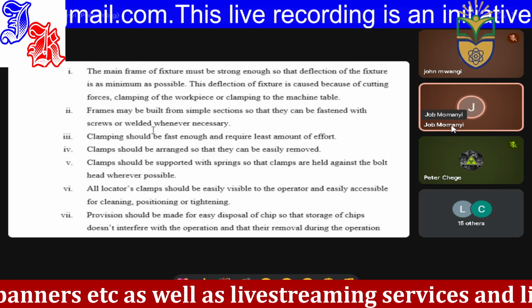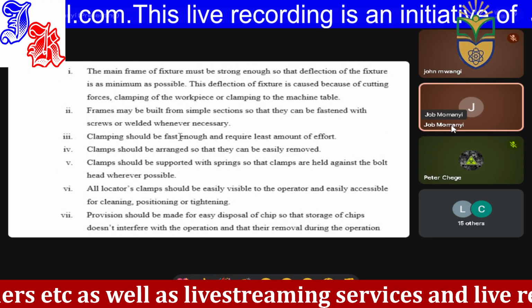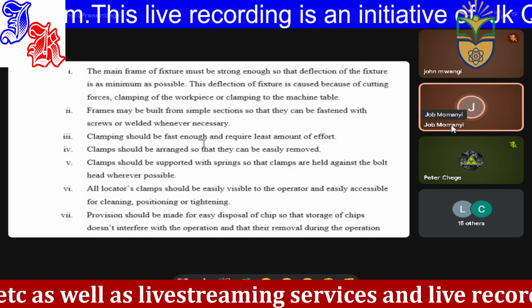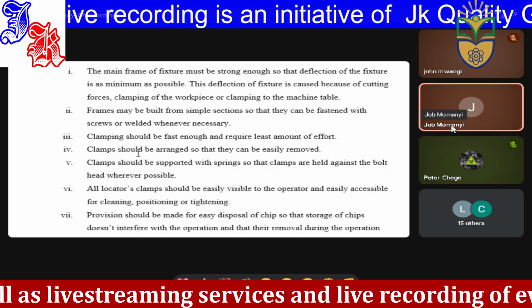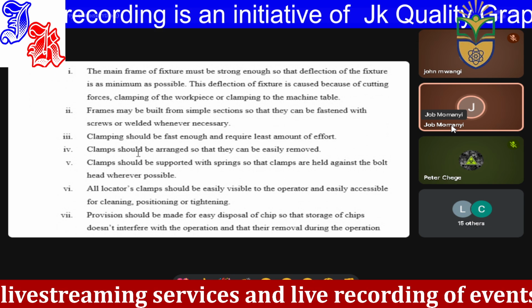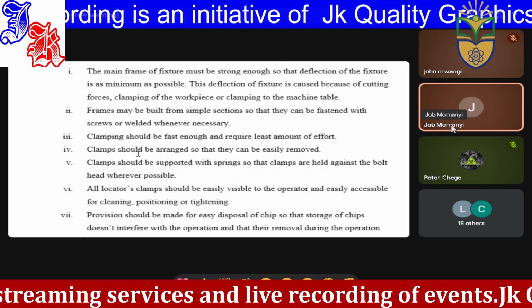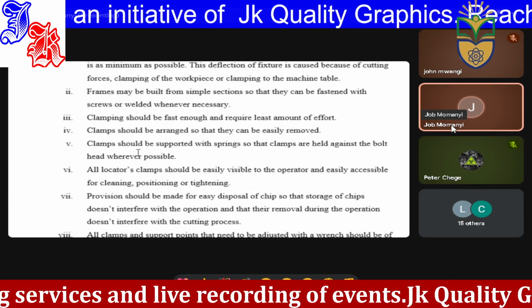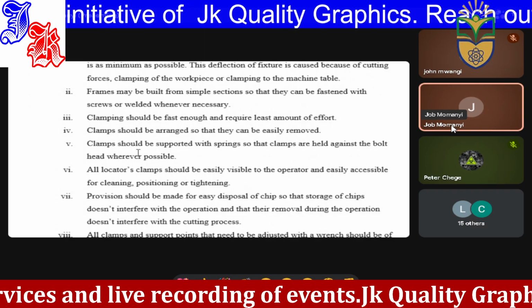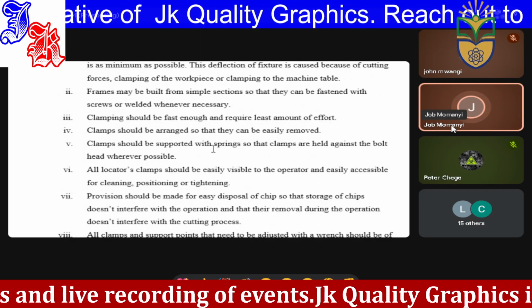Design considerations in fixtures. The main frame of a fixture must be strong enough to avoid deflection. Frames may be built from simple sections so that they can be fastened with screws or welded whenever necessary. Clamping should be fast enough, with a minimal amount of effort.